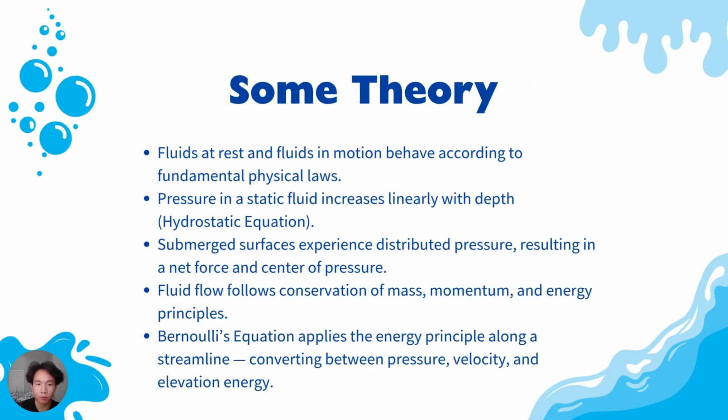Now, before I wrap up, I'm going to talk about some theory. First, when a fluid is at rest, pressure varies with depth due to the weight of the fluid above. That's described by the hydrostatic equation, which we use to calculate pressures on submerged surfaces and find the center of pressure. But when a fluid is moving, we rely on conservation principles like conservation of mass, momentum, and energy.